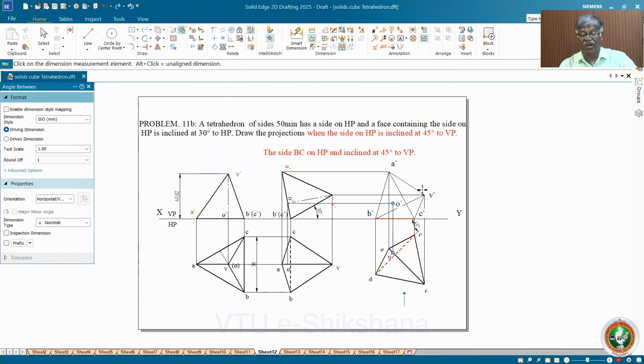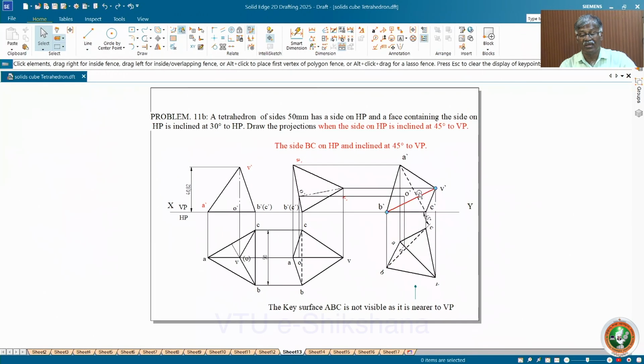Second step is the boundary lines completely dark. Yes, you keep the boundary lines dark. Then the invisible surface is ABC. Out of ABC, AC is not visible, because the other two are boundary. Then this surface is invisible. Definitely this is a crossing line. So, invisible surface, visible line. So this is how you complete the solution for the tetrahedron.